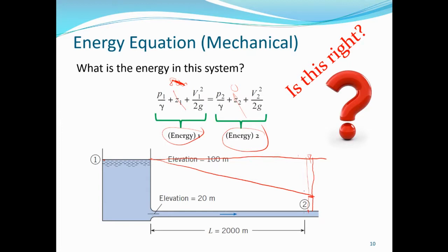So what accounts for the drop in the pressure head? What accounts for the drop in the pressure head? That is accounted for by the velocity head. If we assume the Bernoulli equation applies, we can assume all this represents the velocity head.